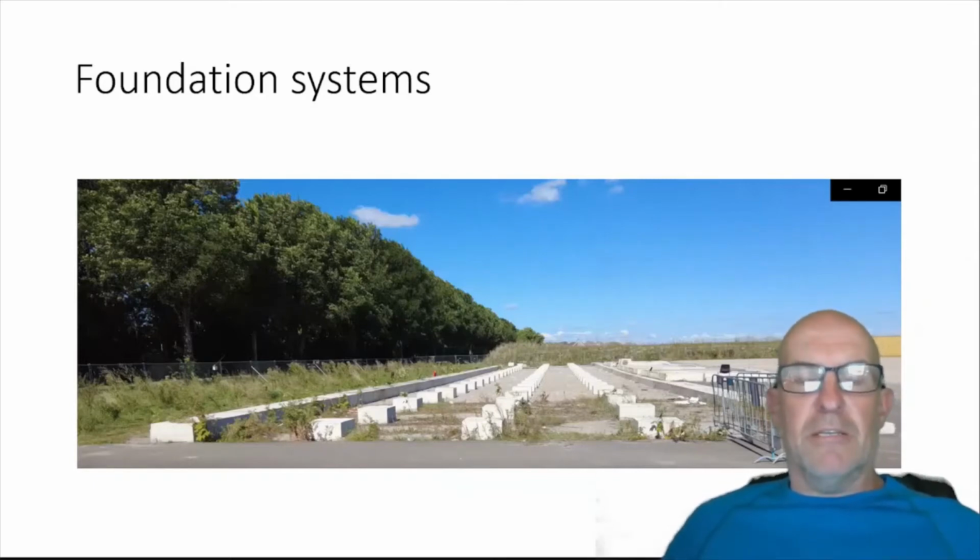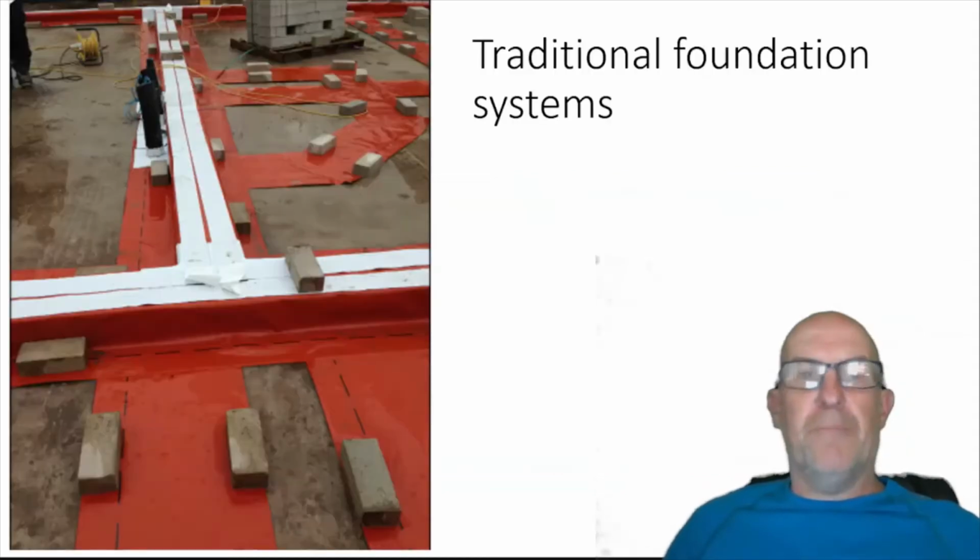Longevity in the buildings. Is gas protection going to be required all through that? Is it likely to be significant enough? And again, you can see the pads sit out the ground there. They're about 400-500 millimeters off the ground level there. But we can also see a lot of vegetation growing up in that void, plus potential for drainage issues as well. So again, lots of factors we've got to think about.